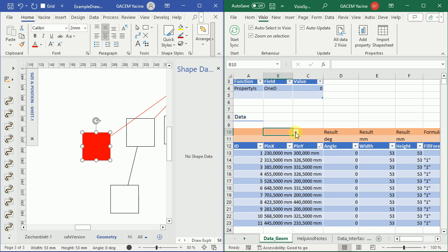So you can use other functions like result int, formula, and so on. Write only is for later on, it's not implemented yet. But let's now try it with result. When you use result, you need to indicate a unit. So in my case, let's say millimeters.